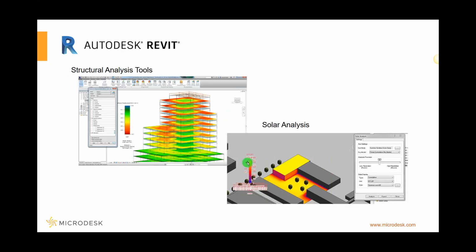The creation of building information models allows us to analyze the models for structural soundness using structural analysis, energy efficiency, and facilities management. Again, much of this analysis can be performed with products inside of the AEC collection. Tools such as Navisworks for collision detection, Insight for building energy and environmental performance, and Robot Structural Analysis for structures and code compliance. Next, let's take a look at Autodesk Insight.